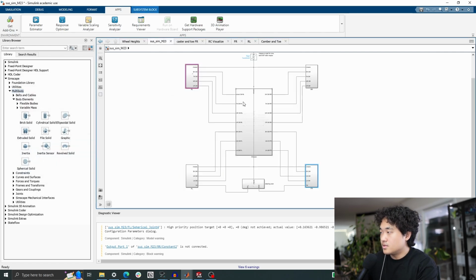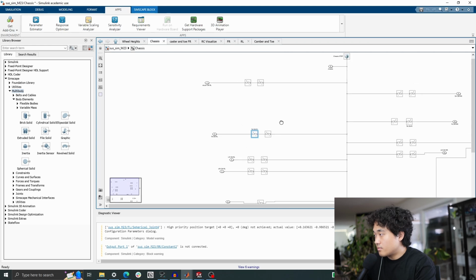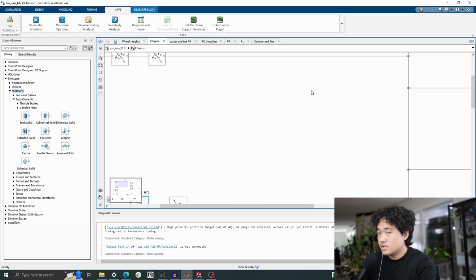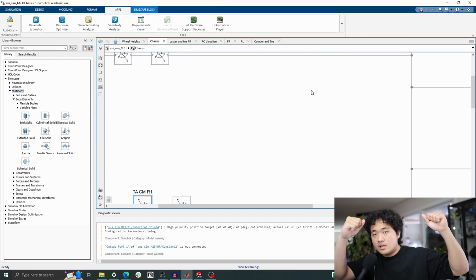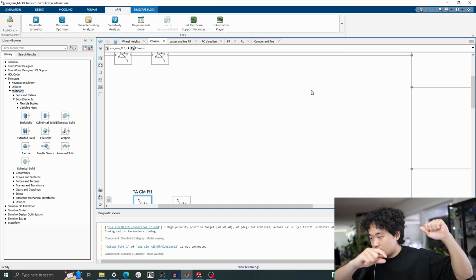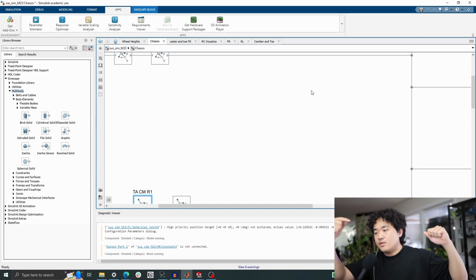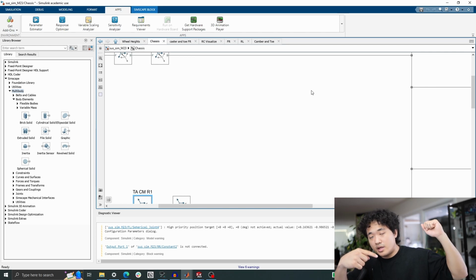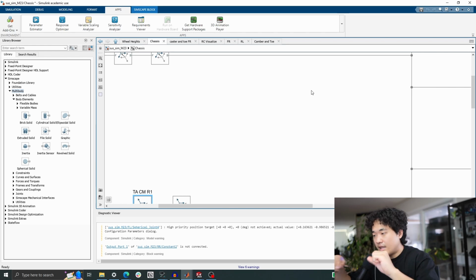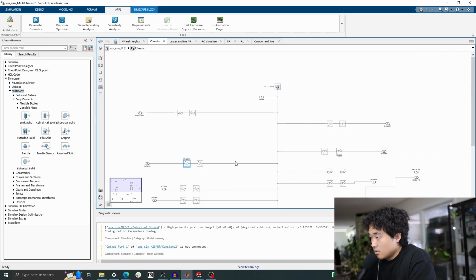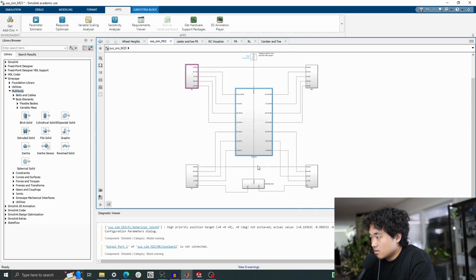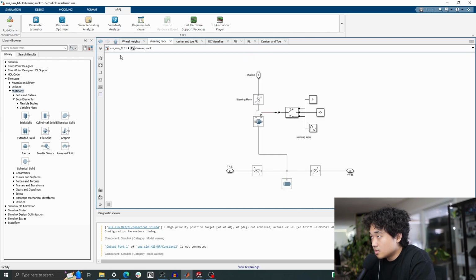And then you do the same thing from the chassis origin. So you have chassis, A-arm, and then the mounting location is located somewhere in 3D space. You go from the chassis origin, do a rigid transform to that mounting location. You go from the A-arm origin, you do the same thing to go to that same mounting origin, and then you could place what you would call, in here and in real life, a joint.